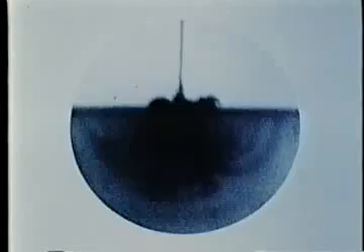If the bubble collapses in an unsymmetrical pressure field, as in this experiment with a bubble at a wall, an internal jet is formed, much as in the case of the missile entry cavity. The velocity of the jet is very high. The impact of these jets on a surface can produce high stresses. Here, a bubble collapses near a photoelastic specimen. The close spacing of the fringes indicates the very high stresses that are induced. Clearly, jet impact is another mechanism which may account for severe damage.